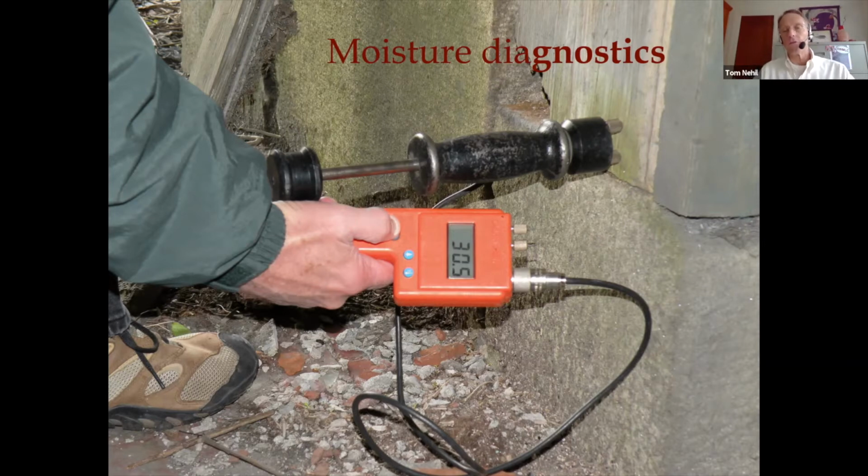On the other hand, if it's greater than 20, it will continue to rot. And so that's a sign to us that we need to get in and take care of some preventive measures to stop the roof from leaking, to prevent water from wicking up from the foundations, and so on. So moisture diagnostics are part of that assessment.